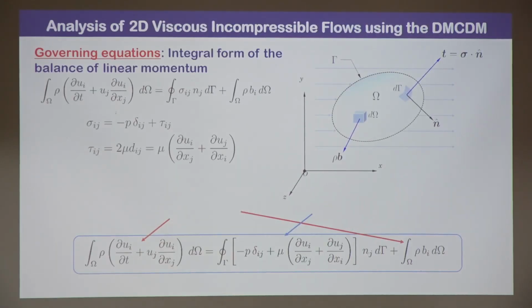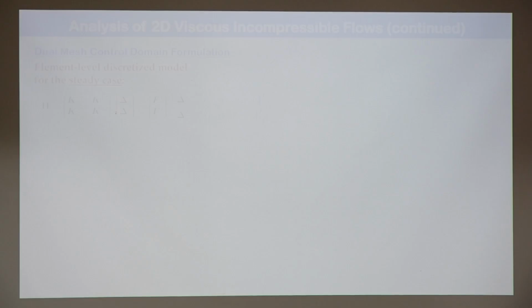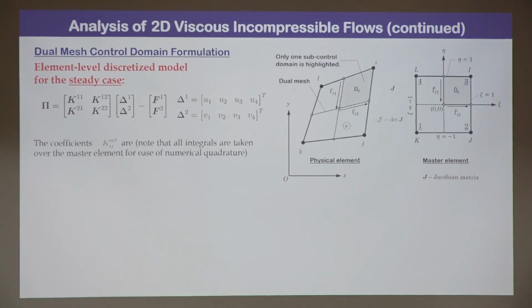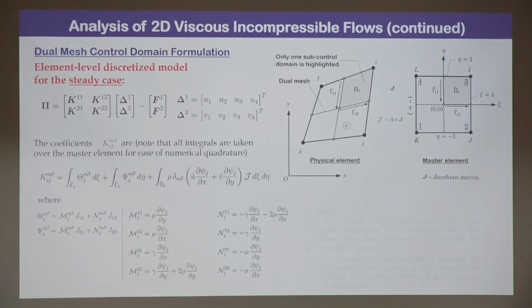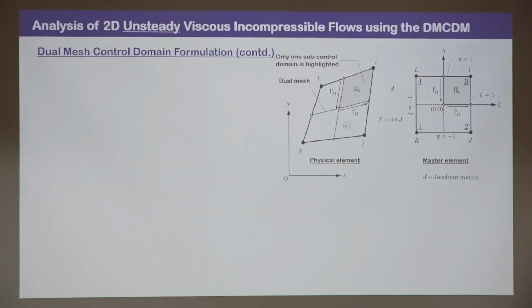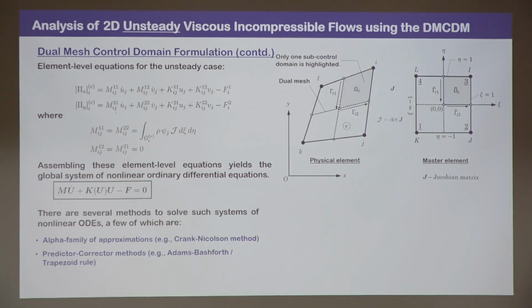We then extended to viscous incompressible flows. This is actually more recent work with the Navier-Stokes equations, which means including nonlinearities. All of this detail you don't have to follow; at the end, you will have this equation. By the way, now it is unsteady also. So the mass matrix, here is the velocity. U itself is velocity, U dot is the acceleration, because in fluid dynamics, velocity is the degree of freedom.